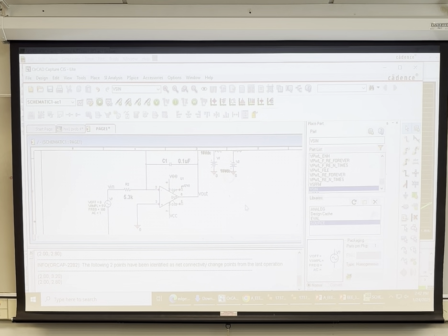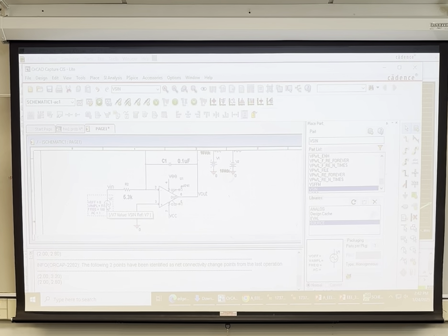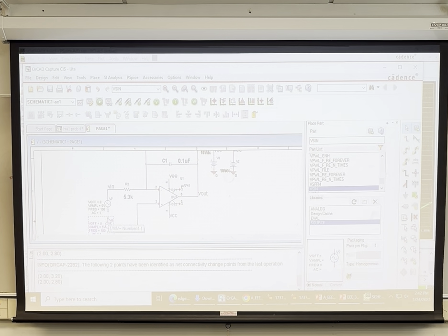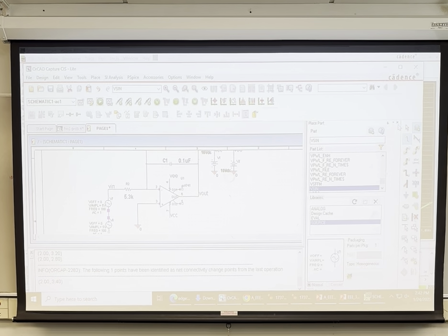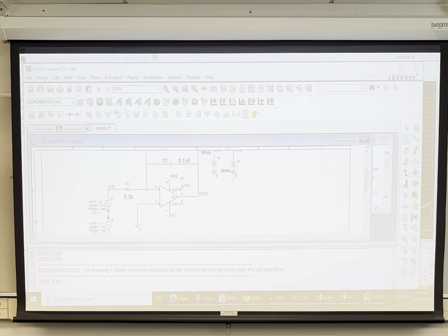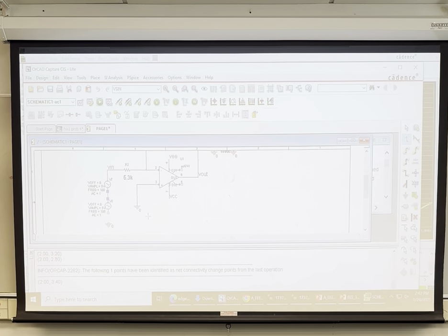Now, you need to add the 30 kilohertz interfering waveform. And the way we'll do that, we'll move this wire, we'll click on this, do a Control C, and then a Control V. We're going to add a second generator in series with the first one. And then we'll add the wire connected. And then our ground wire.